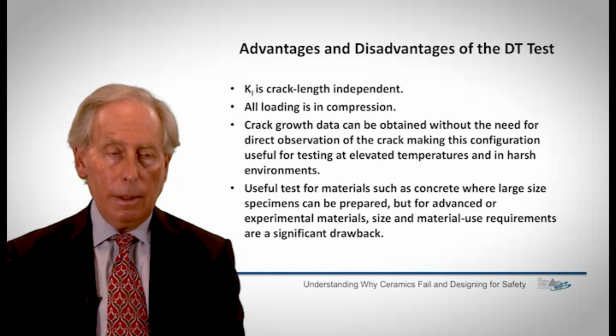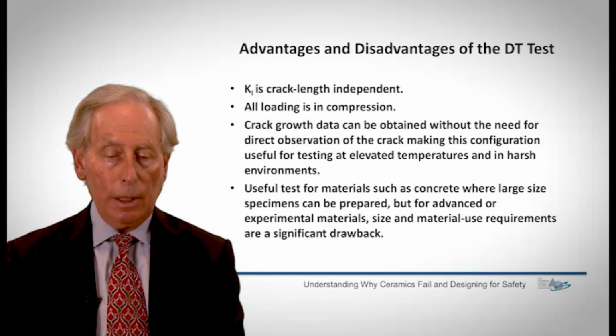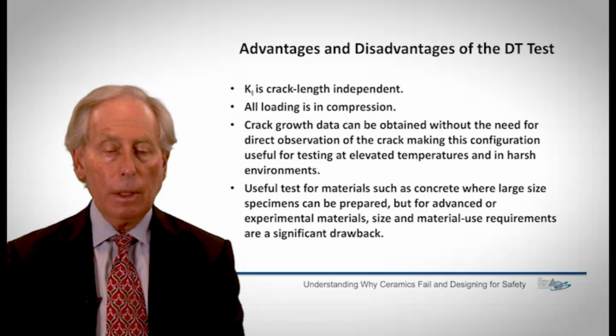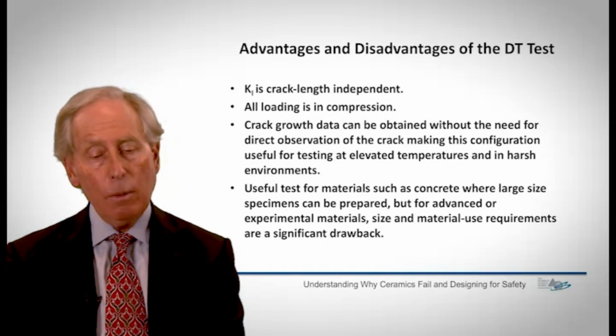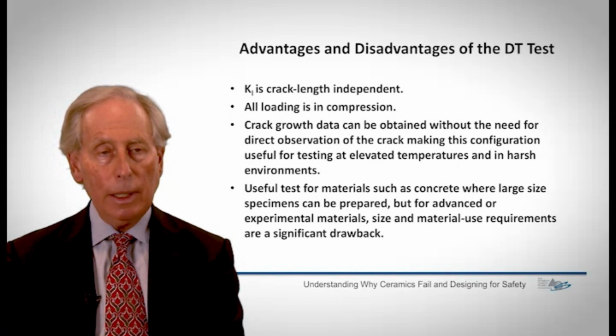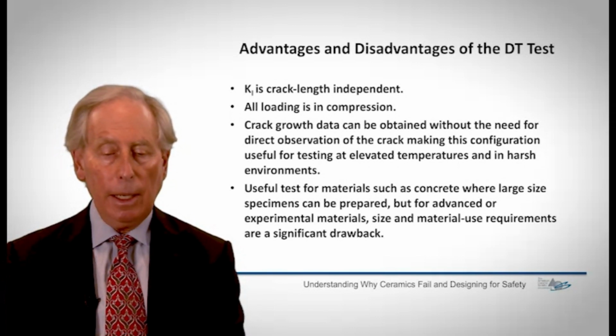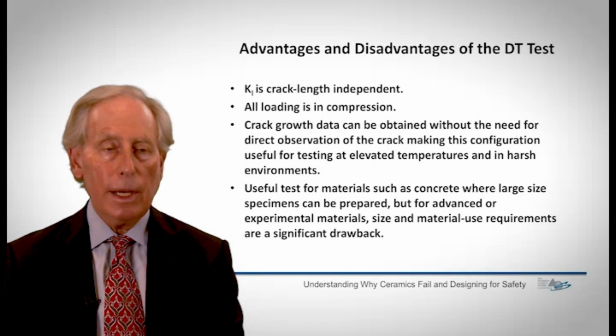So again, there are ways to do this test. I'm not going to show you the details. I would encourage you to again look at that reference, but the crack growth data can be obtained without actually seeing the crack grow. One actually measures the change in compliance of the specimen with the loading on the plate itself. And so again, it's useful for testing at elevated temperatures or harsh environments. You can put it in an enclosed container and get data on crack growth.